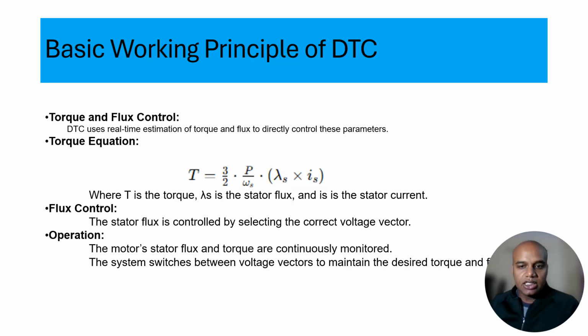The DTC uses the basic modeling concept of the AC motor, whether we are talking about the induction motor, the PMSM motor, or the synchronous reluctance motor. All these three motors have one thing in common: the stators work identically, and all three motors have the revolving magnetic field created from the stator supply.